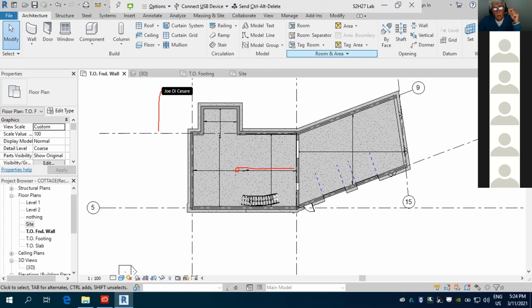This is the beam that you have on your roof, and you have to go in the roof space to see if the beam spans from one end to the other or if there are columns. I think that most likely there are columns, and you don't see them, but they happen to be hidden in the wall on the second floor, and they go into the ground floor. And underneath where the beam is, most likely there's a column right there. So look what's happening. This is all being transferred here.